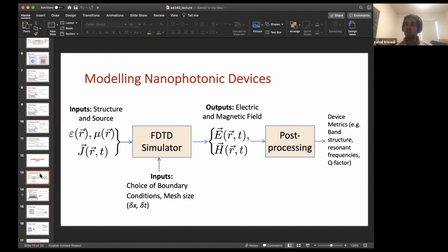I think it's generally a good practice to make sure your numerical simulations are converging. It's not a very well followed practice in my experience, especially in photonics. I note that a lot of people put simulations that are not convergent into papers, which is not the best idea. It's a good practice to see if your simulations change drastically if you reduce your step sizes or if you add extra regions of space between your PMLs and your device. All of those things should be tested out, right? But you shouldn't go crazy about it. You don't need accuracies in your efficiencies that are like 1E-6 relative, or converge to an arbitrarily small amount. But that's one thing you have to keep in mind, and we'll come to that at the end of this slide.